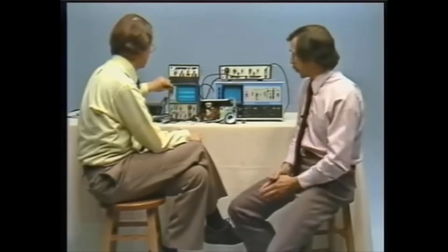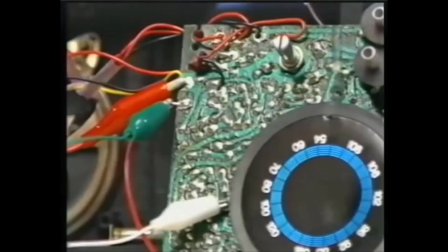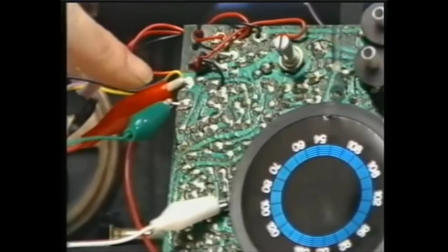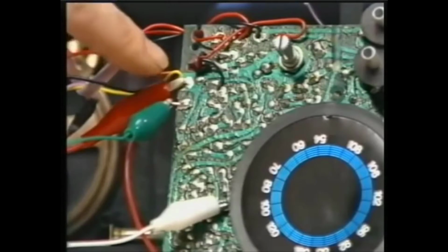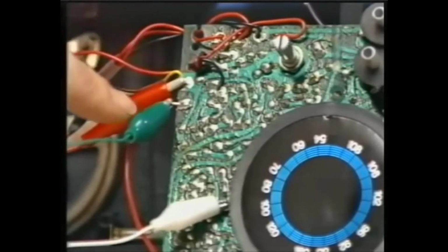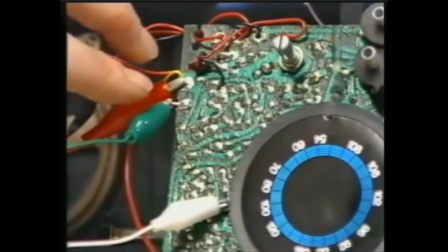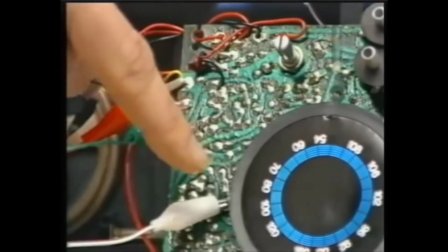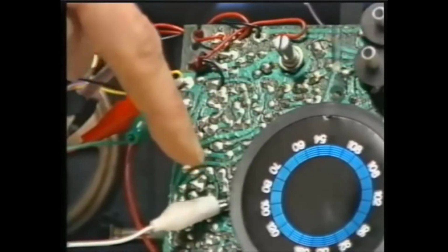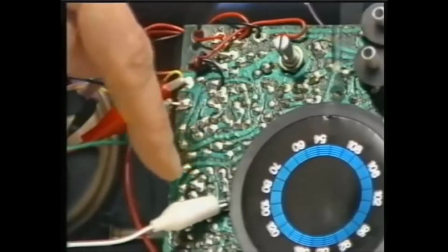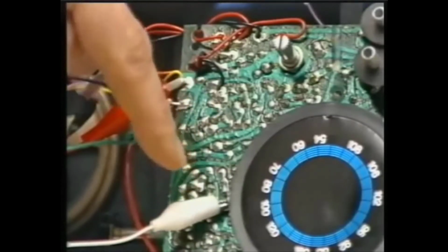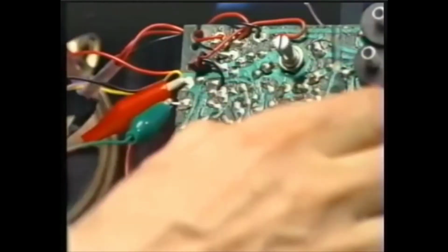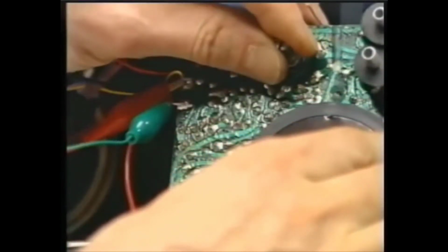So I guess what Sandy has some probes on are the RF input and a ground. And that's right. The red lead here is a ground. It's common for both the signals we'll be looking at. This is the audio. We're actually looking at the signal going directly into the speaker across these two leads. And then this probe down here, which I found by hunting and pecking, is the IF signal, the intermediate frequency signal, with a station on it that I'll now try and get something that sounds reasonable.